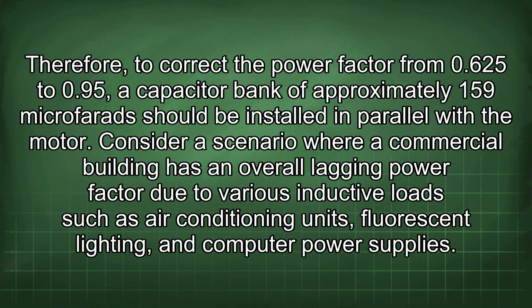Therefore, to correct the power factor from 0.625 to 0.95, a capacitor bank of approximately 159 microfarads should be installed in parallel with the motor.